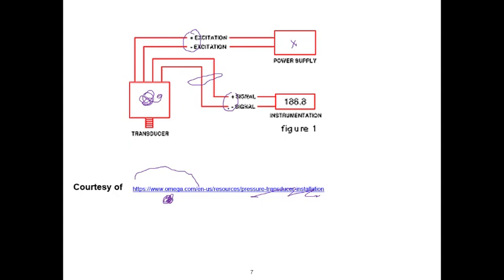If you go back to your notes on op-amp input modes, there were single-ended, common mode, and differential. Common mode is generally electrical noise, practically, by the way. Differential mode is the preferred method because it greatly eliminates or reduces the impact of common mode, i.e. noise, unwanted signals on your control cable. So all these conductors will certainly be in one cable. We want this to be a shielded cable, properly grounded, to try to minimize electrical interference.